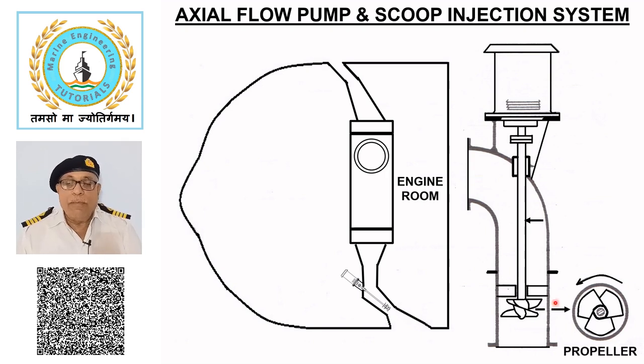The axial flow pump uses a screw propeller to axially accelerate the liquid. The outlet passages and guide vanes are arranged to convert the velocity increase of the liquid into pressure. Ship's propellers and thrusters also work on the same principle.